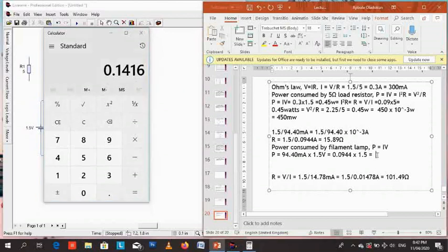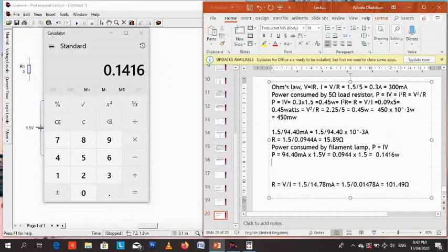According to the LiveWire simulation, there was a drop between the voltage source and the load, and the only thing in between was the ammeter. The ammeter should not cause that much voltage drop. It means there's something wrong with the power source or something like that. Well, let's ignore that minor bug and make use of the actual value and not the measured value.